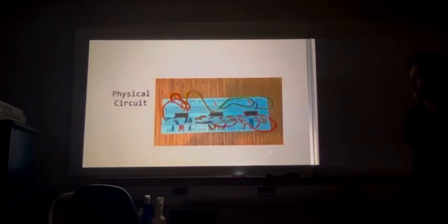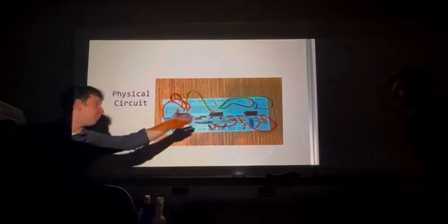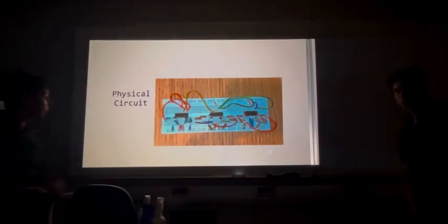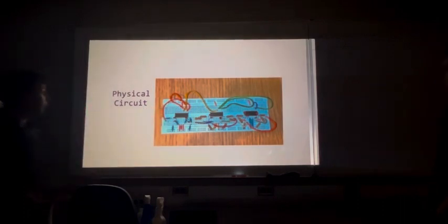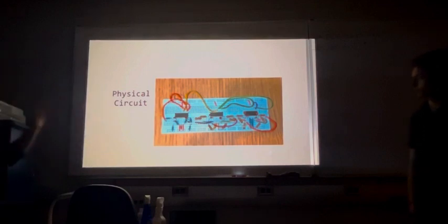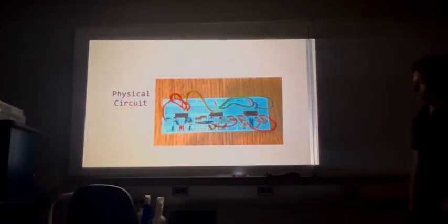All right, so now we have the physical circuit. As related to the last one, we got the bass, mids, trebles. We're using an LM324N quad op amp. So you've got 4 quad op amps there. And this bottom half is the actual equalizer part, the top half is used for the summing amplifier.